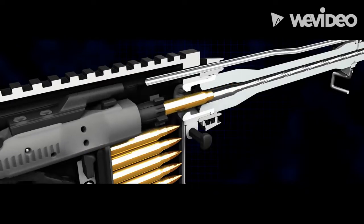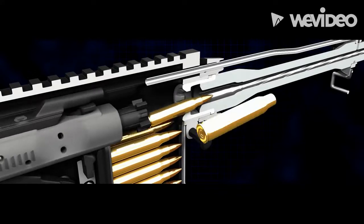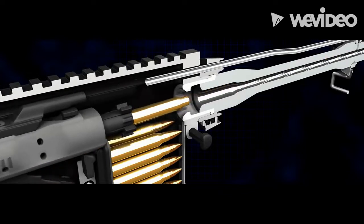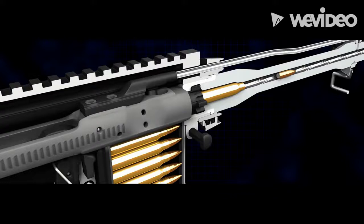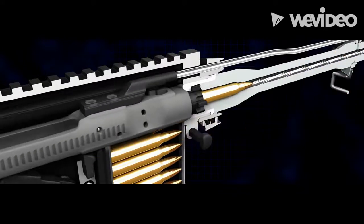This rifle design features a rotating bolt with 7 locking lugs. The bolt's purpose is to chamber the cartridge and keep it locked in place during firing. These locking lugs are rotated into a locked position in the barrel extension. These locking lugs are responsible for keeping the immense pressure of firing in the barrel.